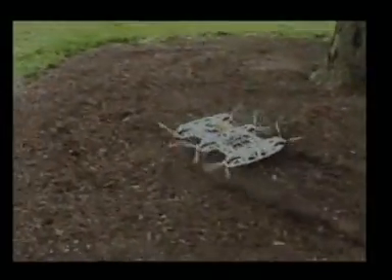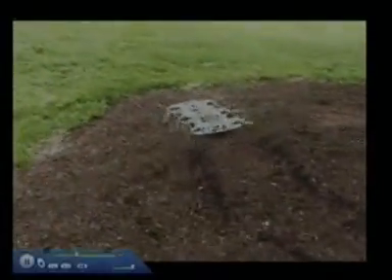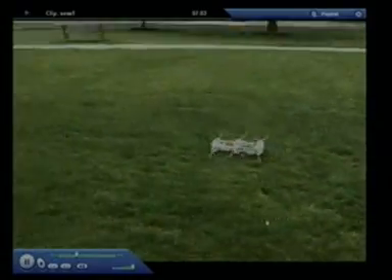The Previous WEGs vehicle uses one large drive motor to propel its six appendages in nominal alternating motions, called a tripod gait. Its three-spoked appendages, called WEGs, combine the speed and simplicity of wheels with the climbing mobility of legs.